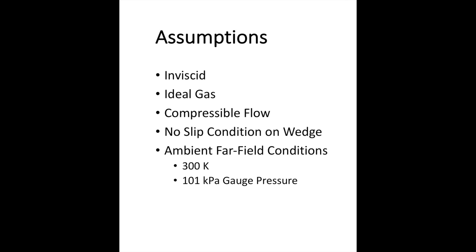The working fluid was assumed to be inviscid and an ideal gas. Fluent's compressible flow solver was used, and far-field conditions were set to 300 degrees Kelvin, and the gauge pressure was set to 101 kilopascals.